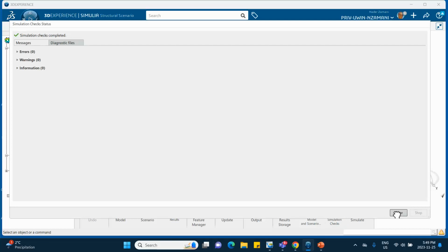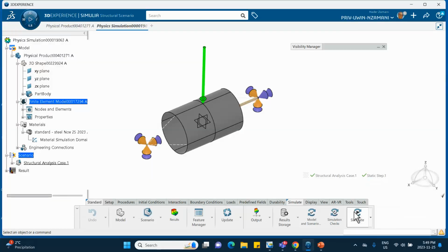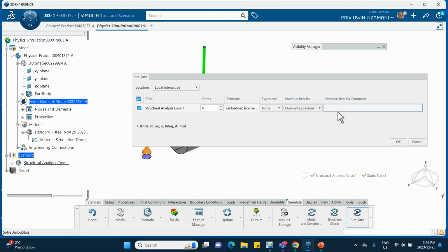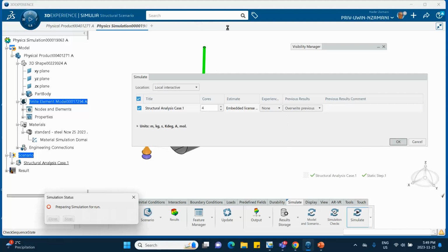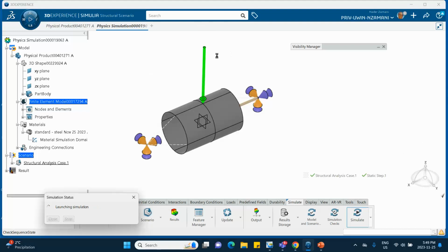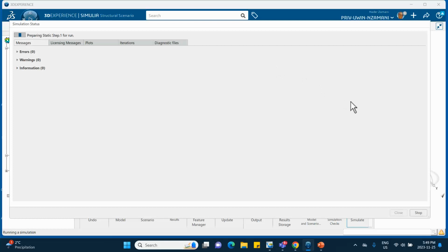Okay. And finally, we're going to simulate. By the way, I didn't check, but this is S4R, no, S4, not reduced integration, okay? Four-noded shell, bilinear shell, but doesn't have an R at the end. If you want, you can change it, but it doesn't make a difference in this problem.